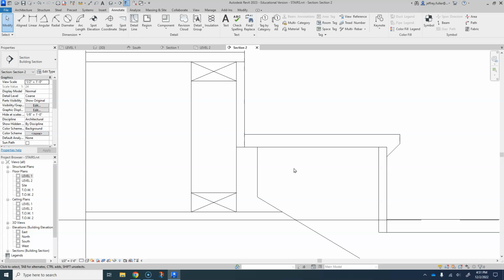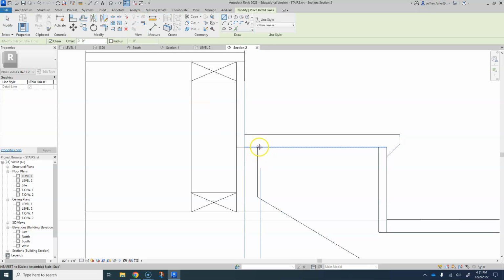So what I'm going to do is use that space, even though I'm drawing a 2x4, which is supposed to be 1.5 inches thick. I'm going to use that whole space to draw one that is in the picture anyway 1 5/8 inches, but we're really going to be representing 1.5 inches. But I just want to go ahead and cover this up. Now what's going to happen on the job site, probably, because it's 1/8 inch larger, which isn't really that much, that will actually benefit our riser by placing a little bit of pressure up against that riser. Of course, if the gap is too big, they would go in and probably put a shim or something in there to shim that up and make it all fit.